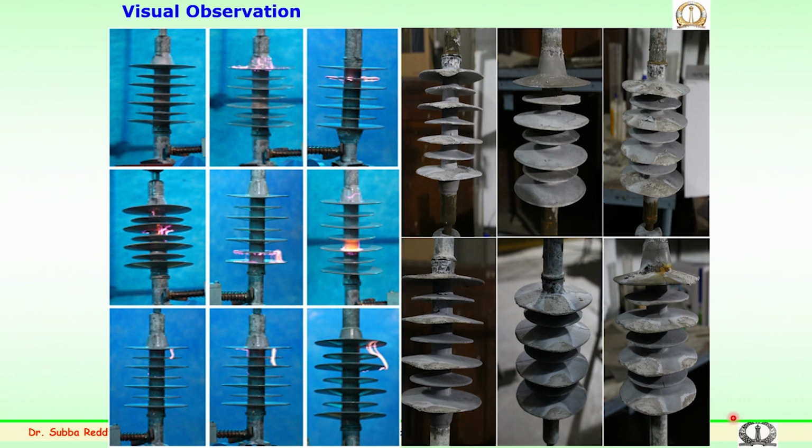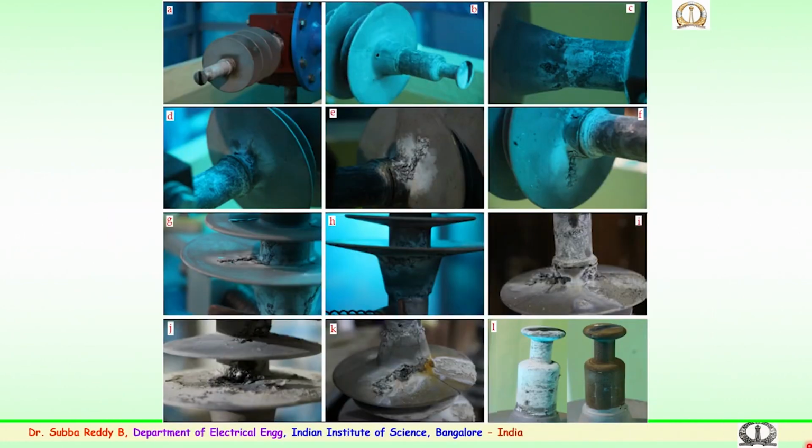This gives an idea to see how the sample performs over a long period of time with the rotating wheel type of arrangement. So, further to that, not only the surface degradation, in some places puncture signs have been noticed and pin or metal corrosion has happened on many of the samples, and in particular in acidic treated samples more degradation, more surface rupture and the pin getting corroded have been visible, much more compared to the normal contaminant.